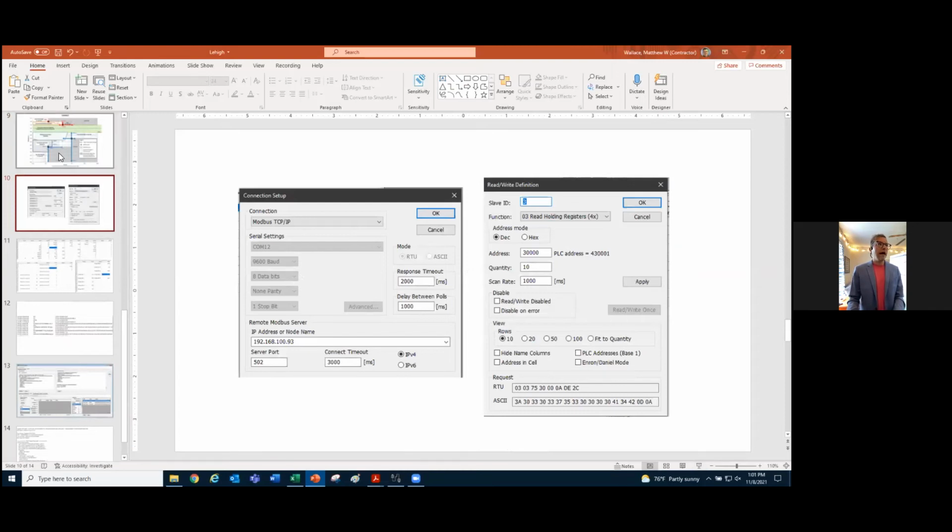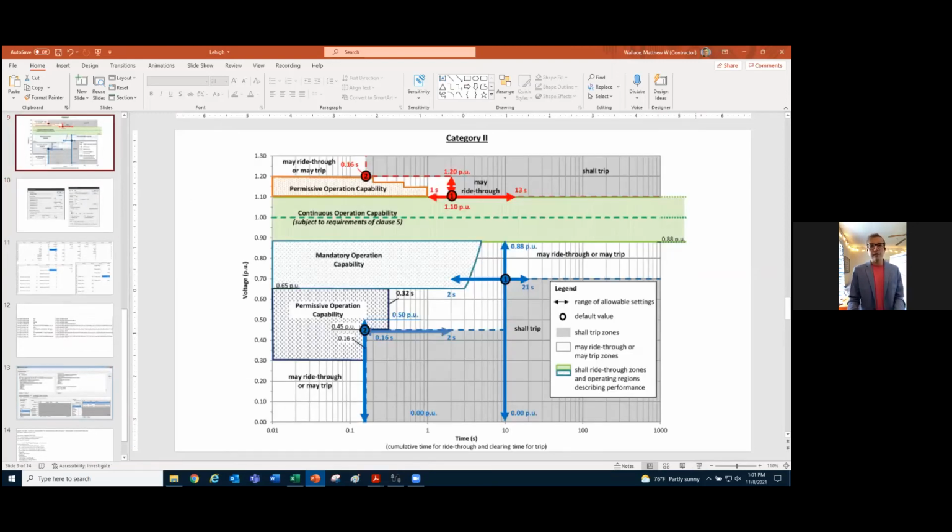So if you look at the communication interface, it's actually section 10.7 of the IEEE 1547-2018 standard. It says that DERs shall have a standard communication interface, and through that communication interface, you can access the settings of the grid support functions. And that the communication interface needs to have one of 3 communication protocols: either Modbus, 2030.5, or DNP3.